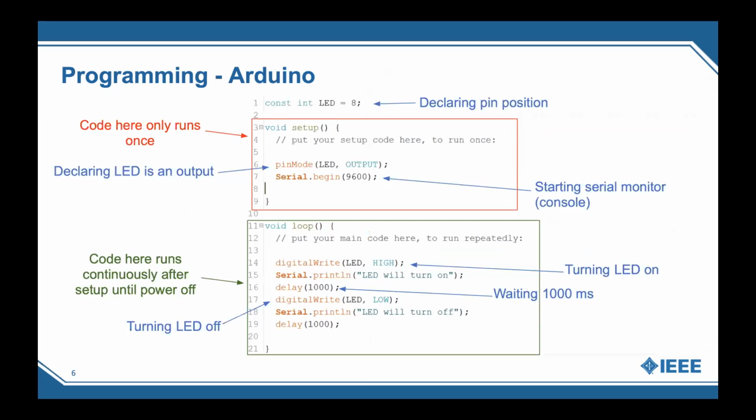So this basically goes over the setup of Arduino. As Gerardo said, it's based on the C programming language. You can see the first red box is void setup. This would be the same thing as where you declare your variables in C. So this has pin mode. We declare LED as an output. Then the program's going to know that when we talk about LED down here in the body, it is an output, so it's going to know to send out information.